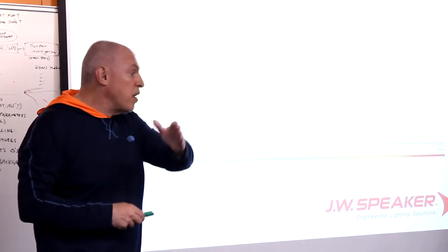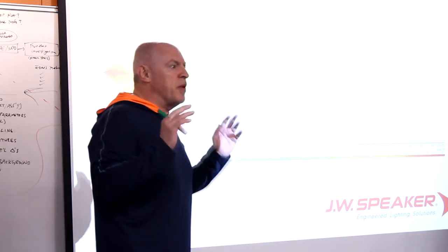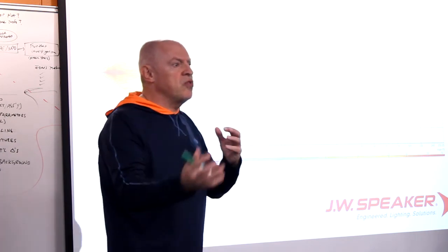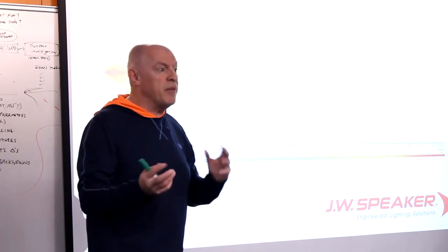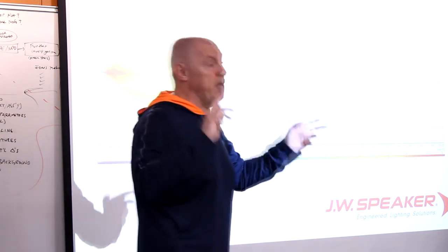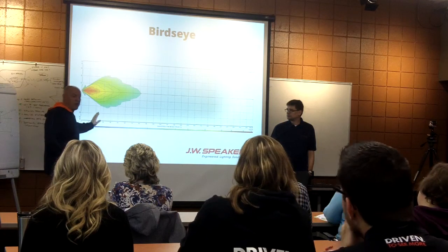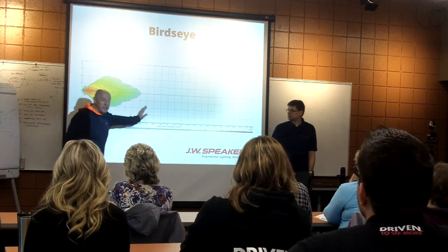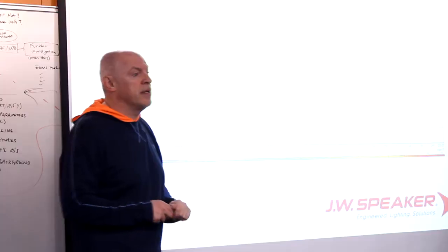There is also a North American unit, which is the foot-candle. But most people everywhere else use lux. Usually the ratio between low beam and high beam is, the Holy Trinity, 1 to 3. A good low beam reaches around 100 meters. A good high beam, 300 meters, reach down the road.